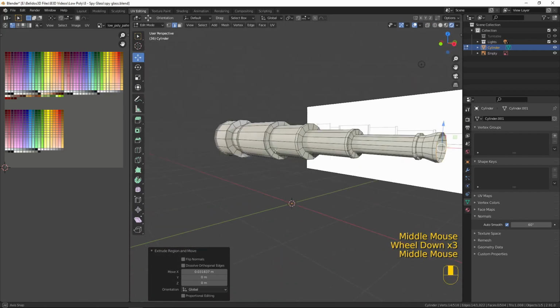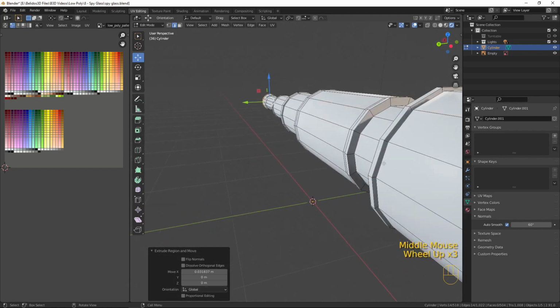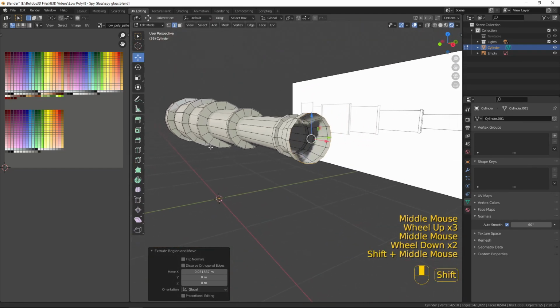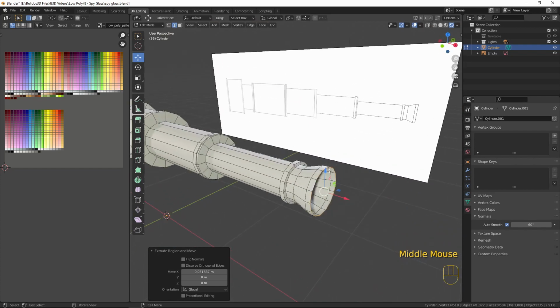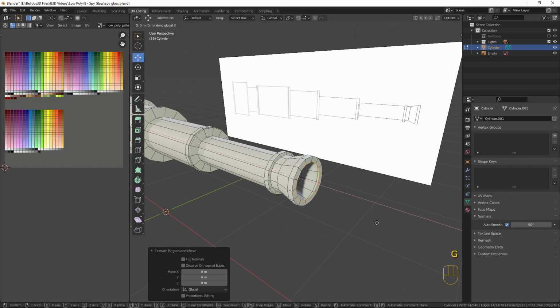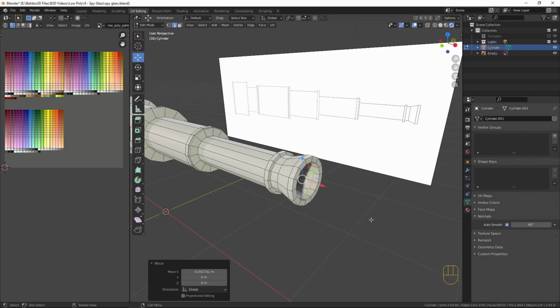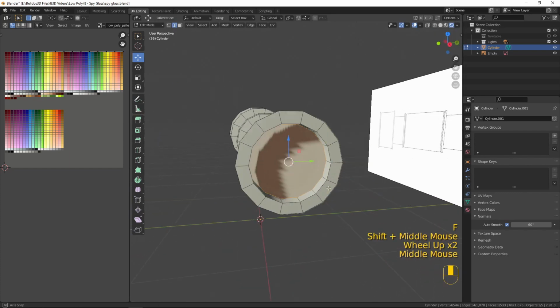What we need to do now is do the ends of the spyglass and create lenses for them. So what I'm going to do is, with this edge loop selected, I'm going to press E to extrude and right click and scale it down to about there. Then E to extrude and GX to bring it back, just a little touch there. And I'm just going to fill this cap in with the F button.